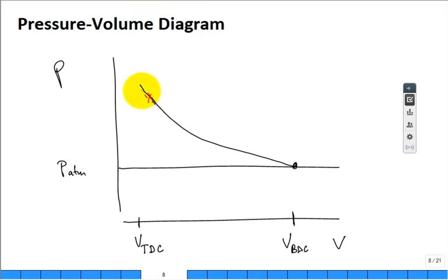It leads to a rapid increase in the pressure because of the combustion. Huge heat release, all trapped in a small volume. Temperature goes way up, pressure goes way up. But then it's going to be expanding through the power stroke. And as you expand through the power stroke, you get down to where another valve cranks open.